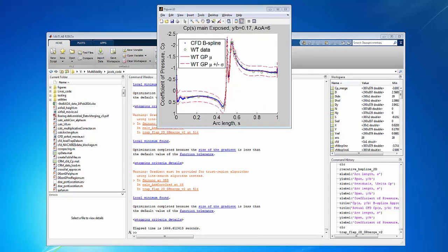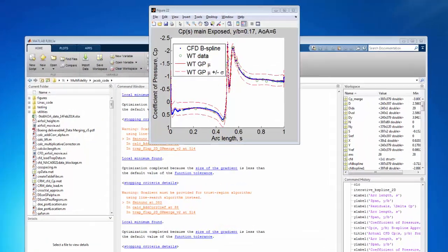As you can see from the MATLAB screen output, we have a Gaussian process additive combination of neural network plus squared exponential covariance kernels. The CFD simulation results calibrated the wind tunnel data Gaussian process surrogates. We're using a linear set of scale and location correction terms on the CFD results. The calculations here are for the spar or main wing section of the NASA trap wing.